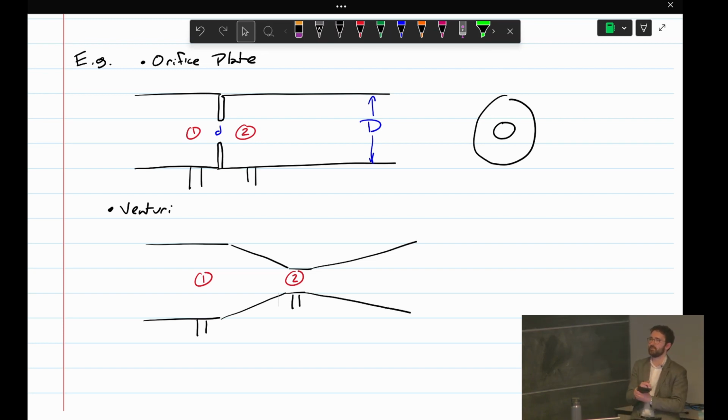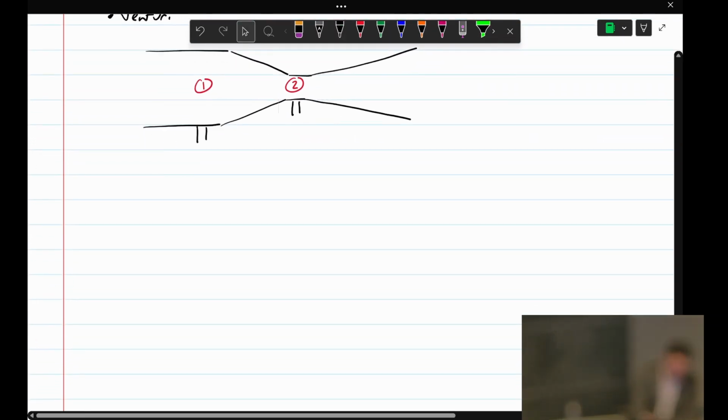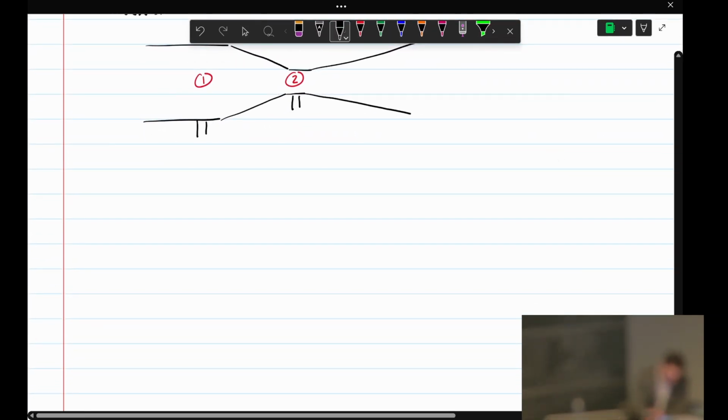So in places where it's not that expensive to add additional pressure to the fluid, like some steam supplies and refineries, they'll use orifice plates for flow measurement. But for a pipeline that moves liquid across the country, they don't use orifice plates. One, because the velocity is so high, these things wear out. And two, because, like I said, a major cost is providing pressure for those.